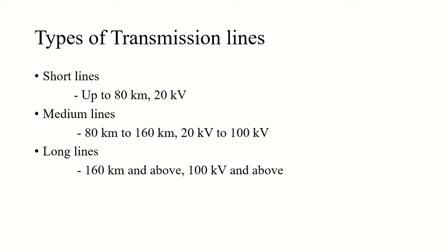So that is your medium line. Then there is the third one, which is called long lines. The transmission lines which have length more than 160 kilometers and line voltage above 100 kilovolt are generally termed as long lines or long transmission lines.